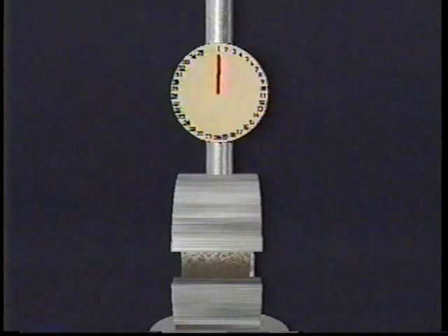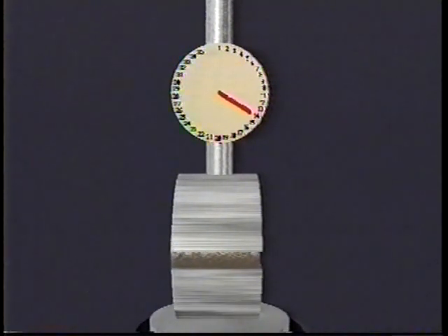Flow is a measure of the elasticity of the specimen as it is loaded. This is a test specific to flexible pavement materials such as hot mix asphalt, or more properly, asphalt concrete, or AC. A flow meter is used to determine the amount of movement or strain occurring between no load and the maximum load for the test.